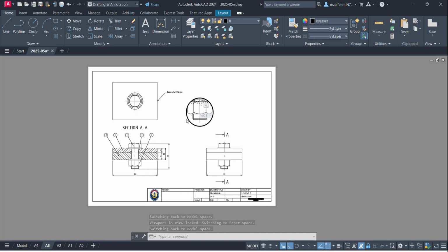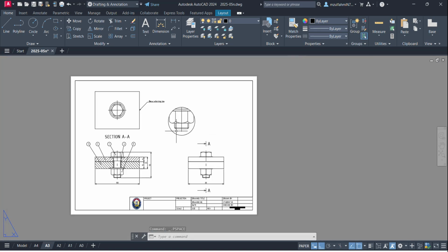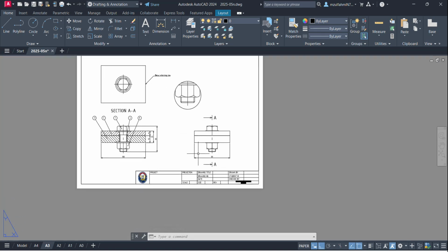If you want to change viewport, for example here, this is the second viewport that I create. Control R, you can change between viewports. This is this viewport, and then Control R, this is this viewport. So you can change the viewport here, and then Control R again here, and then if you want to do, just click model, so it will become something like this.